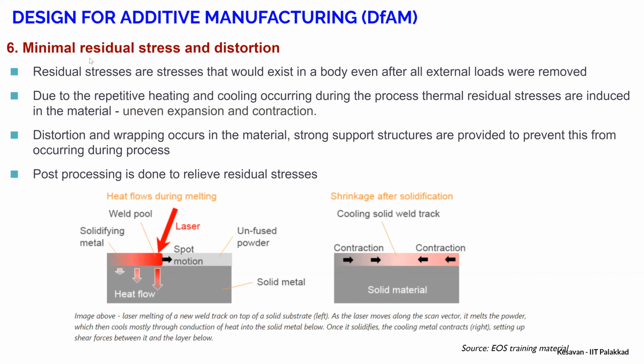Those stresses are called locked stresses. They are generally classified into two types: tensile and compressive stresses. As long as those stresses are compressive, no problem, that will add advantage. If those stresses are tensile, then that will reduce the limiting value of the material. Let's say the component has 1000 MPa yield stress, and you have 500 MPa tensile residual stress, then the net is only 500. You can design only for 500 MPa. So that's the effect of a residual stress.